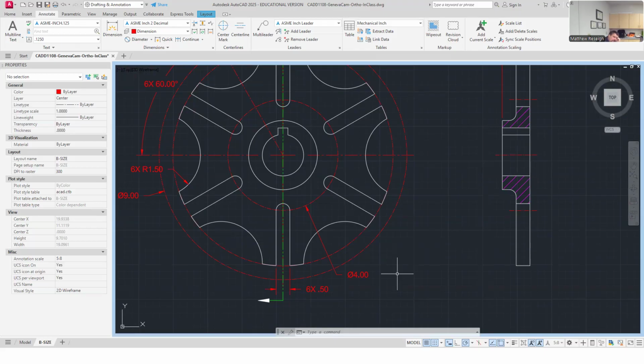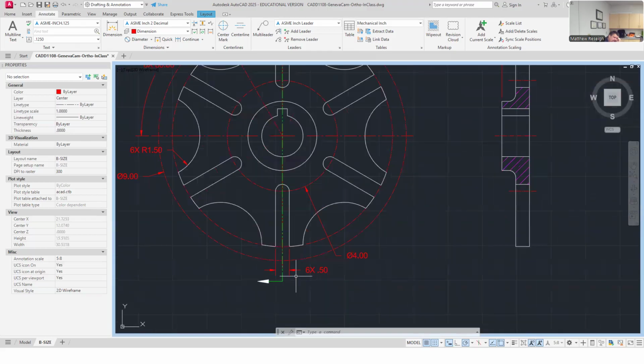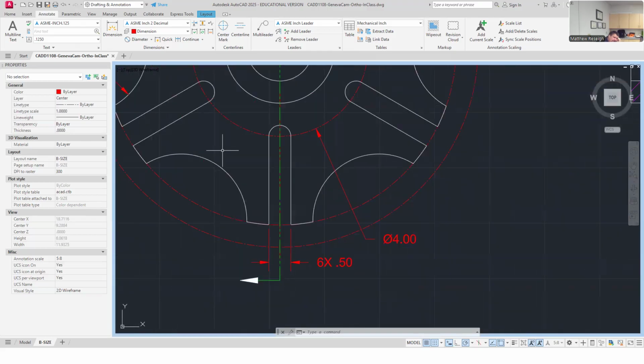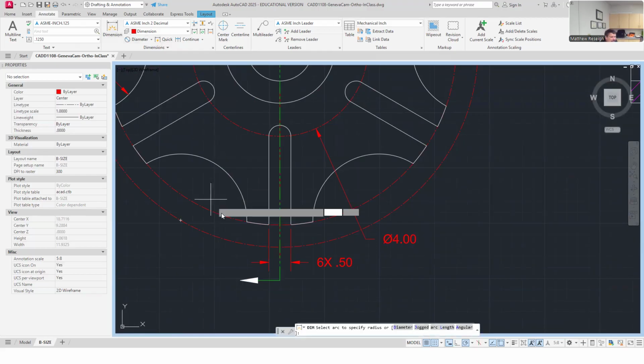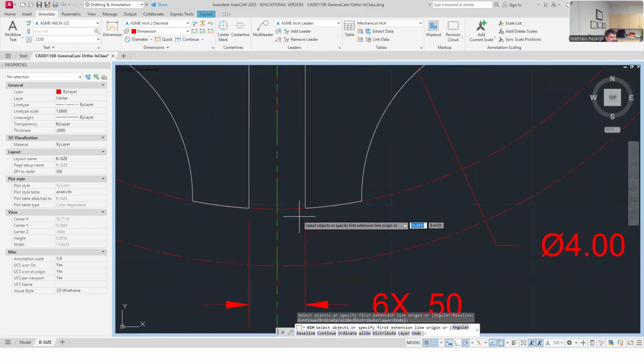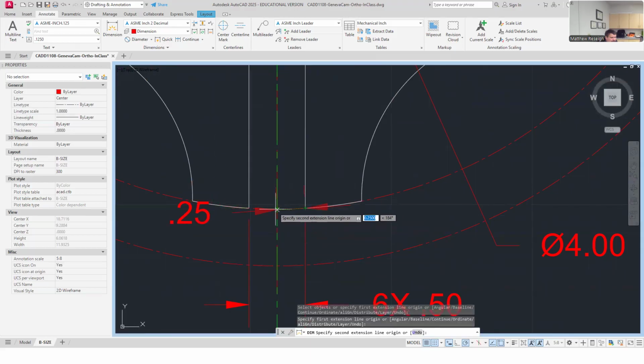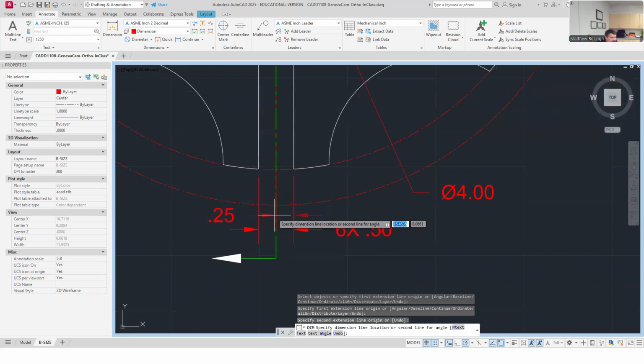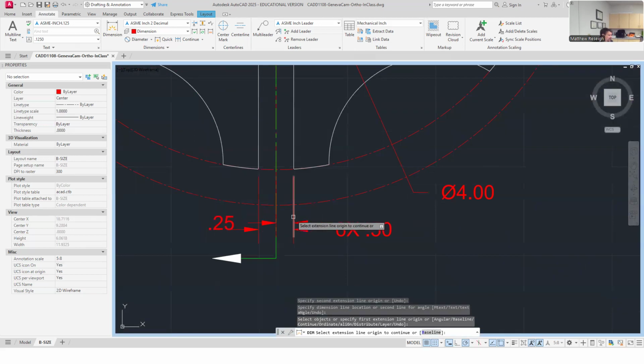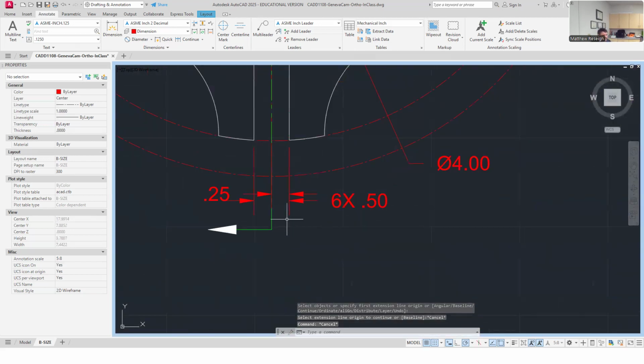So that's size and location and amount, quantity of them. The other thing I could maybe add as a location is that it might be nice to know that these are kind of like a keyway. I could see that one dimension maybe I was missing in my first one is just how far off center it is, just to truly show, to make sure that it's not vague, that these are a 1/4 inch away from center. So this is going to extend out.